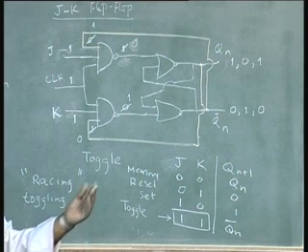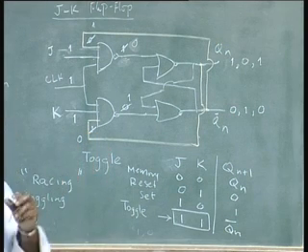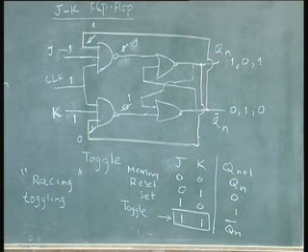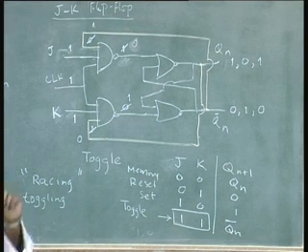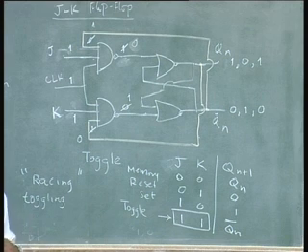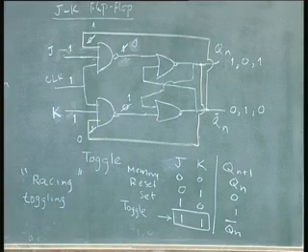The only way to avoid it is to make a clock which is very small in width. Clock frequency should be extremely high, which is also not required. Why should I operate my flip flop at that rate? So, what are the other ways in which I can remove this racing condition?